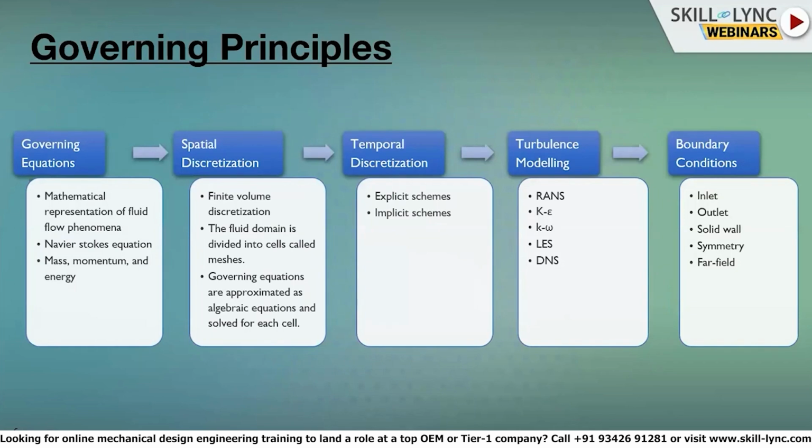In the Navier-Stokes equations, we have the momentum equations, x, y, z momentum equations, and there is a continuity equation. So we have mass conservation and momentum conservation, and wherever heat transfer is involved, we couple these momentum equations to energy equations. Otherwise, if heat transfer is not involved, we are just solving the momentum equations plus the mass conservation equation, that is the well-known continuity equation. So we have the governing equations now in mathematical representation.